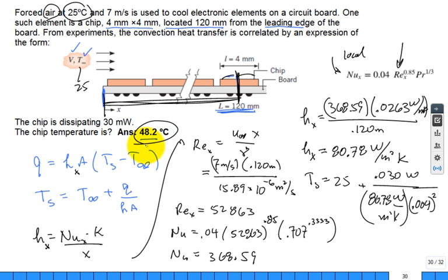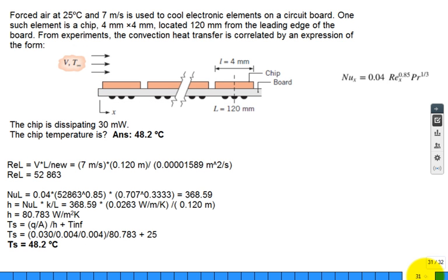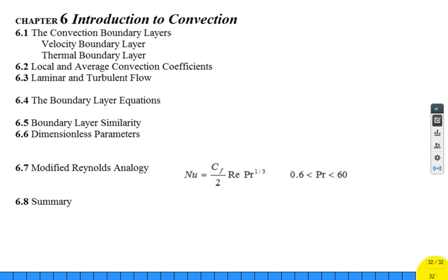Okay. All right. We're about out of time. There's that solution. Maybe I should have just shown you the solution. And let me just try and emphasize what we've covered today. The name of the game when you're talking about convection is to find h. How do you find h? Find Nusselt, because the Nusselt is defined as hL, or let me put an x here, over k.